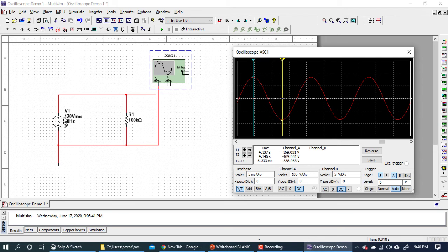So what is the RMS voltage? Well, it stands for root mean square, and it's very close to like the average voltage. It's not really the average, but it's close. So you can see that the voltage is constantly changing. It's going from 169 back to 0, and then negative 169 back to 0, and then 169 and back to 0. And it's doing this 60 times a second, over and over.